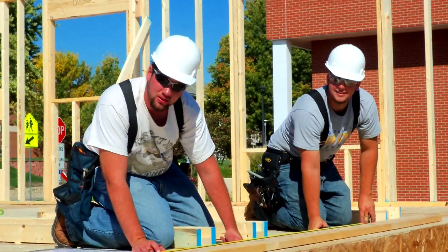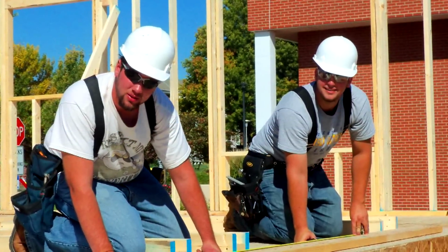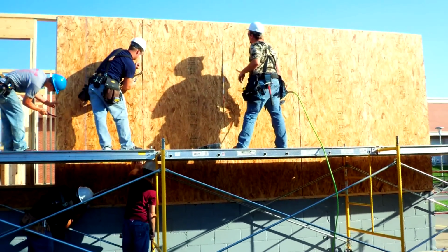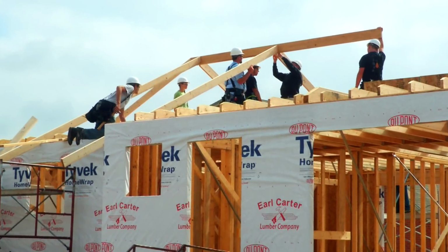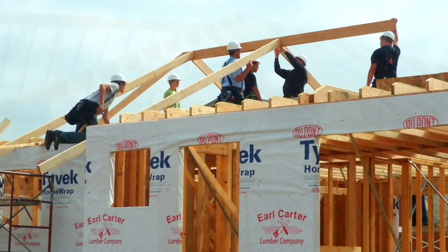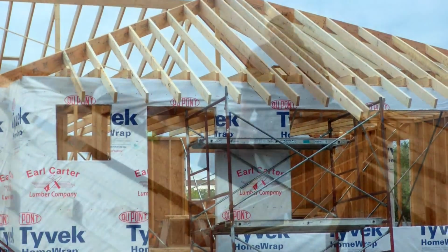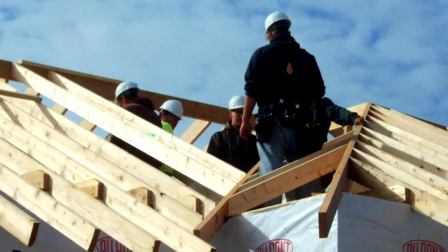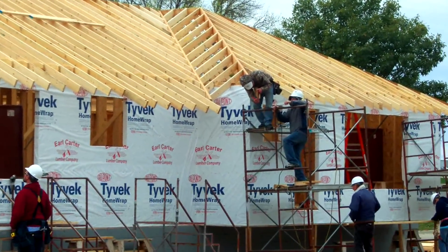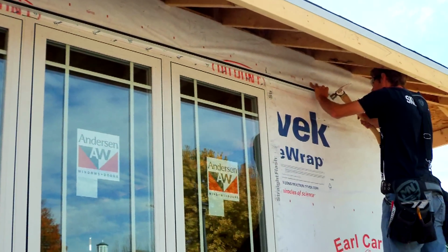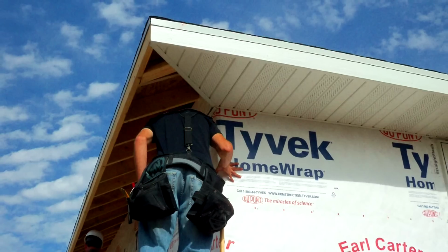The walls are then laid out, constructed, and set into place. OSB sheathing is applied to the exterior of the stud walls and covered by a house wrap. Construction of the roof system is the next step and is stick framed, so students learn how to lay out, cut, and install rafters. The roof area is then sheathed and shingled. Upon completion of the roof, windows and exterior doors are set and the aluminum soffits are installed, followed by the